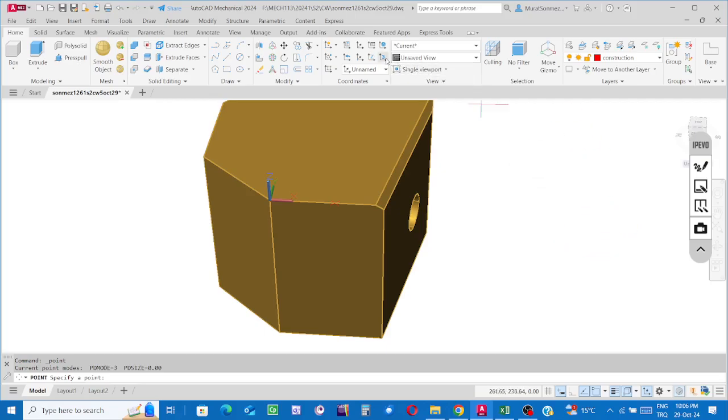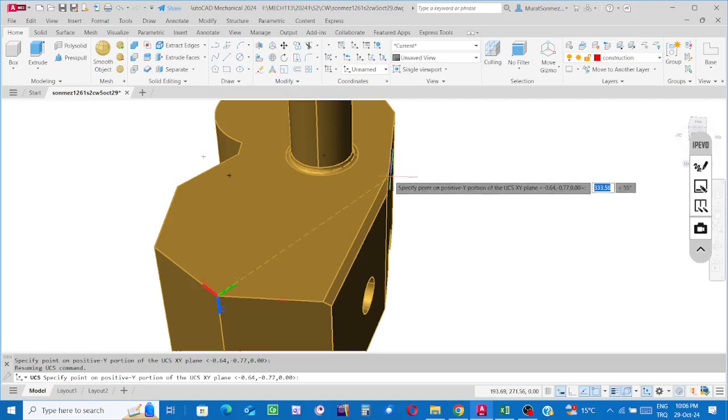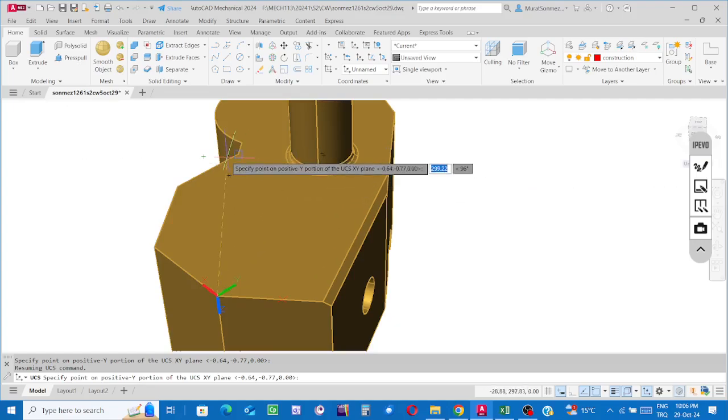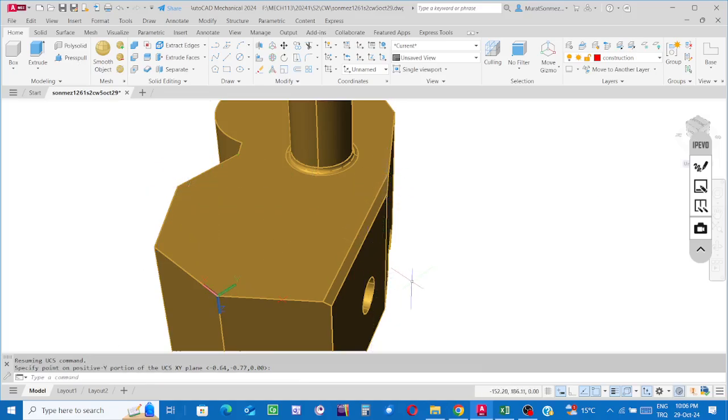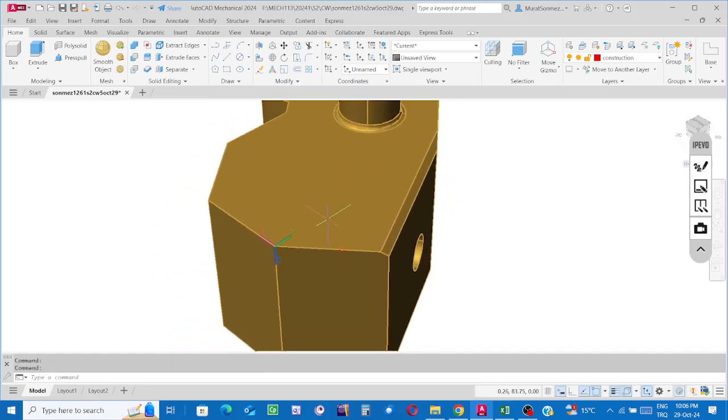And then restart the coordinate displacement process, and then indicate the corner as the origin, indicate this characteristic point as the second point along the positive side of the x-axis. Okay, y-axis, you may indicate one of the characteristic points, this one, that one. Not a matter, it is going to be perpendicularly oriented with respect to the x-axis. Okay, now restart the point marking process.